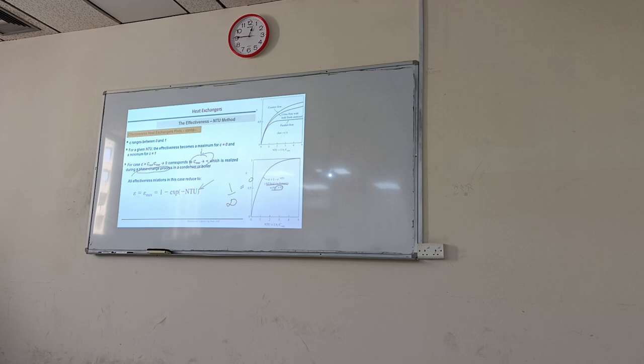In the boiler and condenser of a steam power plant, one of the fluids is changing phase. That will result in the highest effectiveness, and beyond that, it has already reached 1. But this is theoretical. Actually, of course, you will not have C exactly equal to 0.